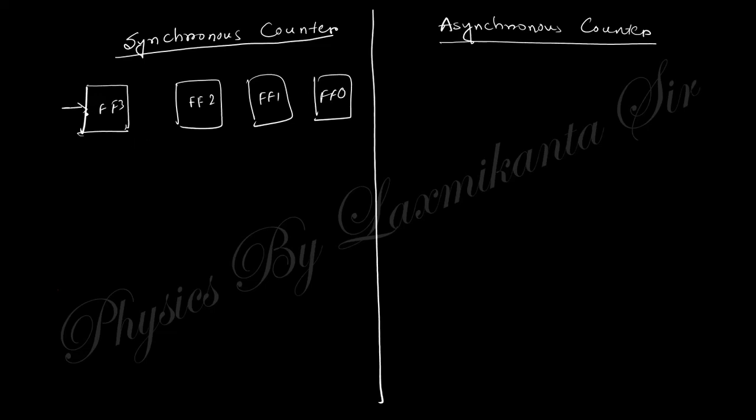All the flip-flops are triggered by a single clock, and this is an edge triggered clock, not a level clock. You know, with a level clock there is a problem of race around condition.